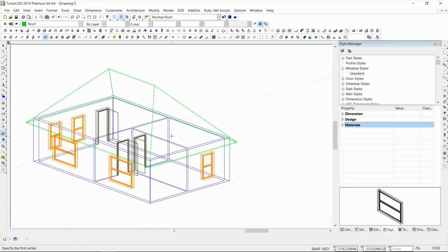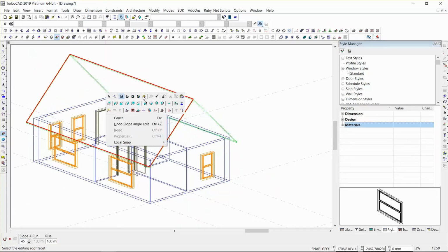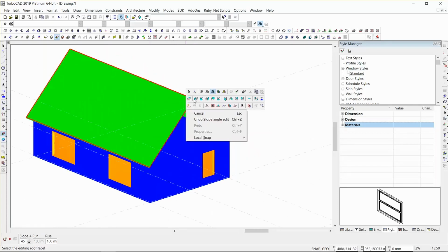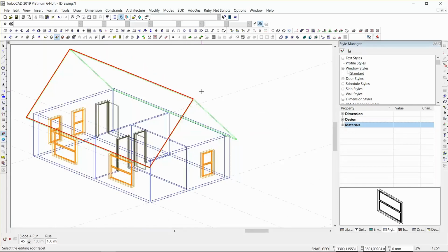Right, so now it's got a normal roof to all four corners. But I can give the roof a slope, or change the slope on any side. For instance there, and I'm going to do it there as well. Right, so see what we've got now. Is that the default at 45? Yeah, you can change that whenever you want in your properties, but that was the default, yes.